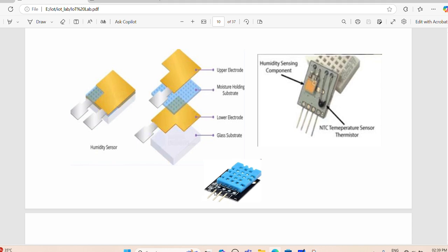So make sure that the supply voltage to trigger this module is given through 3.3 volt, which means pin number 1 is the one which you can utilize to connect it to this VCC. So 3 volt VCC should be given to turn on the system, and for ground, you can utilize any ground connection. So this substrate, the moment you dismantle it, you're going to find the view of this module something like this.